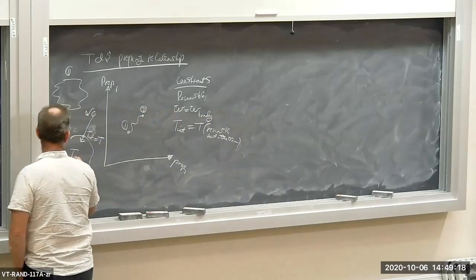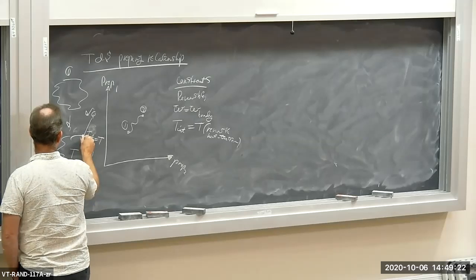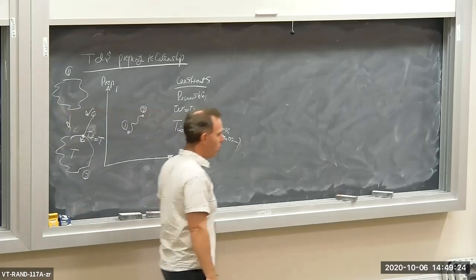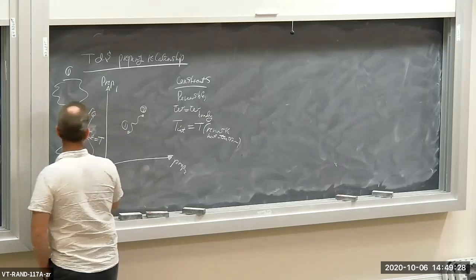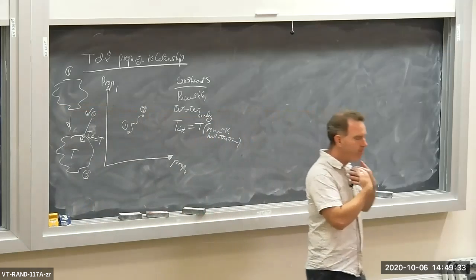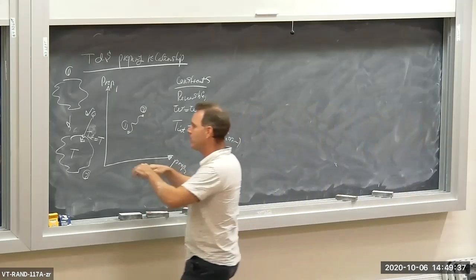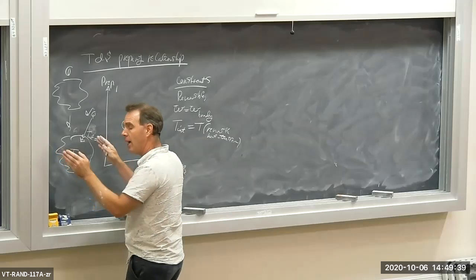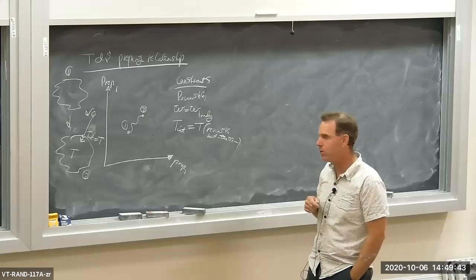So here's the temperature of the system. There's the temperature at the surface of the system where the heat transfer flows across the system boundary. These temperatures better be the same, else as the heat flows into the system, we would have heat transfer across a finite temperature difference, and that would be irreversible. So those temperatures must be the same, okay?